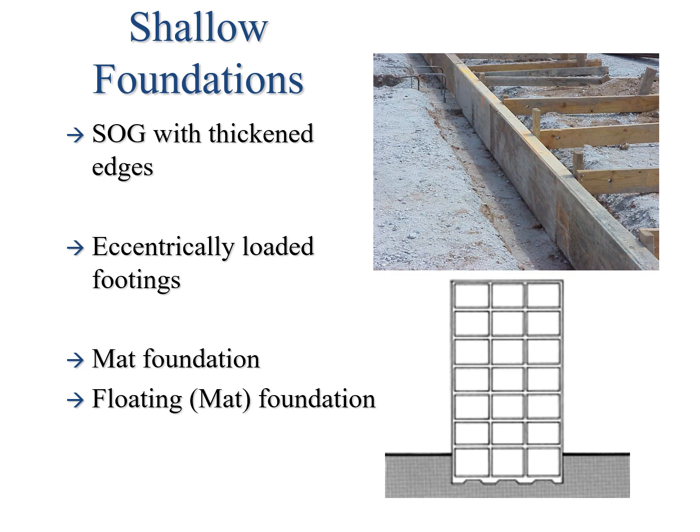Then finally you have the floating mat foundation, which is isolated from the earth. The idea with the floating mat is that the weight of the soil displaced is equal to the weight of the foundation. So the soil bearing below has no worry, as the capacity of the new foundation does not exceed that of the soil that was displaced. You're using the same weight there, and then you have a lot less to worry about.